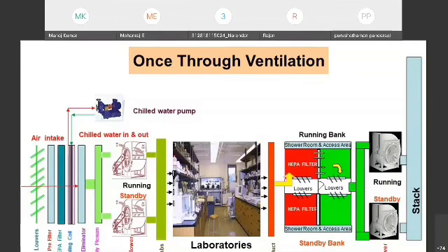This is how heat exchange takes place in a cooling coil, and now the air temperature will be at around 15 to 16 degrees. This air again passes through a water eliminator, where, in case there are water particles in the air, they get separated. It is also called a drift eliminator.